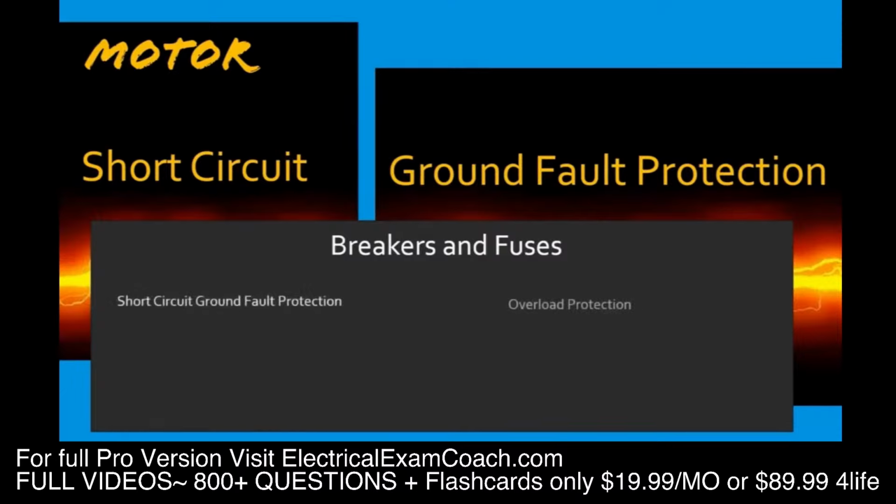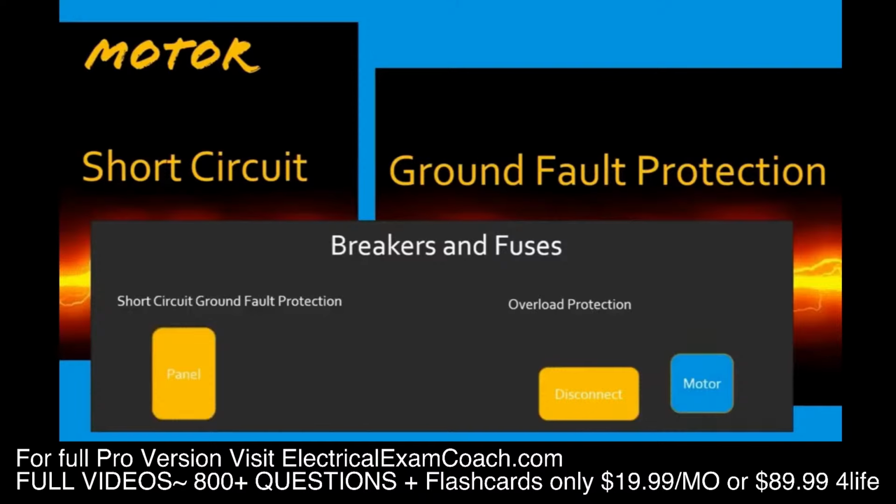Okay, so we have both the types of protection. Let's imagine that this is a motor. Next to the motor, there's a disconnect. And then feeding that disconnect, there's a panel. At the original panel is where you're going to put your short circuit ground fault protection. At the disconnect is where you're going to put your motor overload protection.